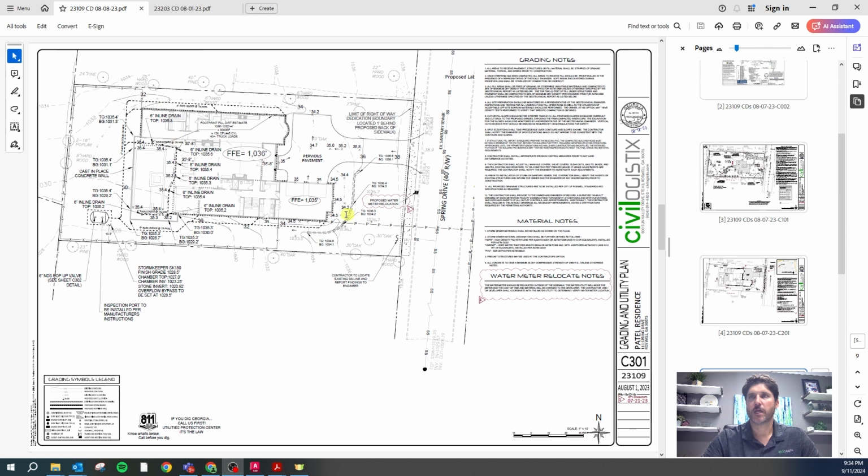So you'll note that the contour line is like a slice through the earth. It's always going to go in one side and go out the other. It could come in over here and go back out here, and then another one at the same elevation come here and go out, but it's always going to have two. They're always going to come in pairs. It's always going to go in and always going to come out.